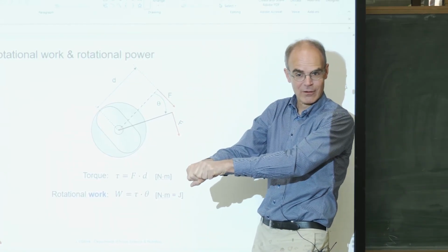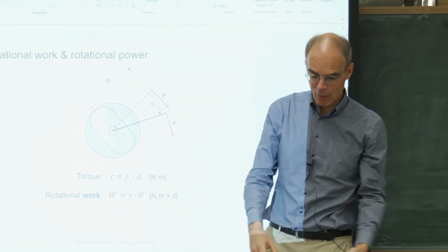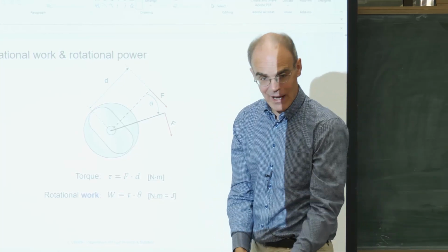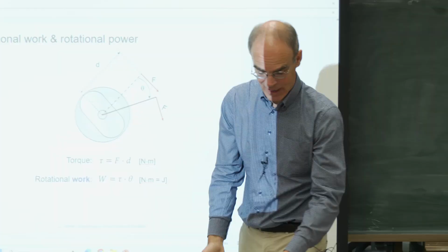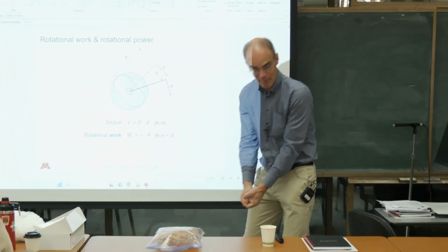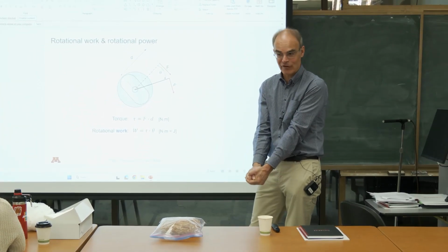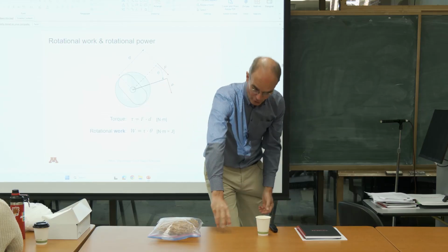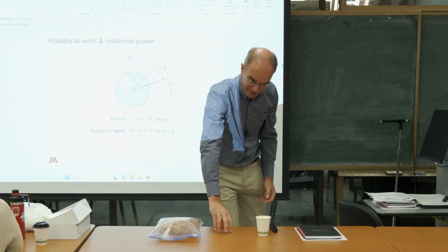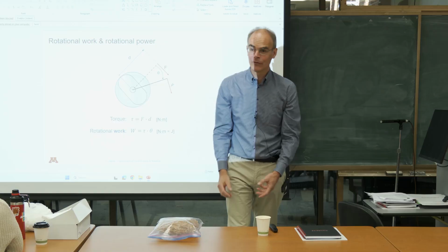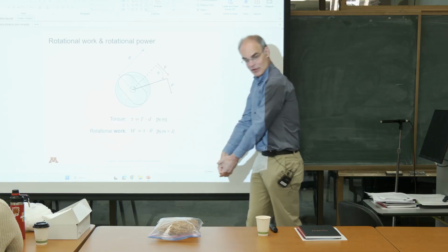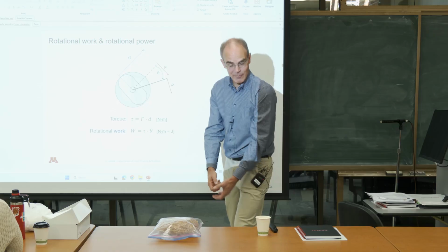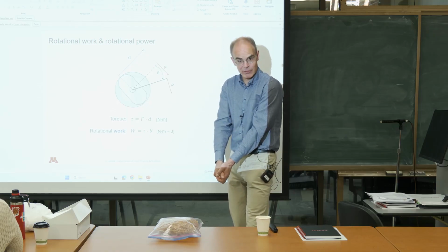Yeah. If I have let's say a bolt which is really fixed, I want to have a key for that, which has a little bit of a distance, because my force is a given, because that's how strong I am. The actual torque, the moment I can actually exert on that bolt, is larger if my key is longer.